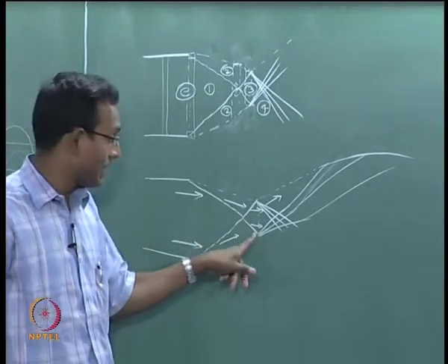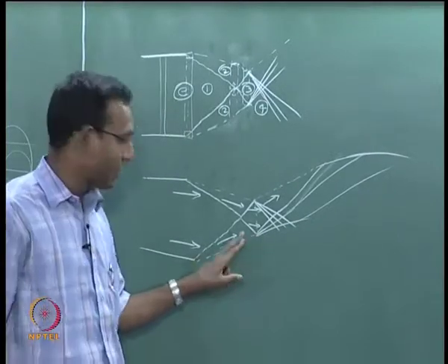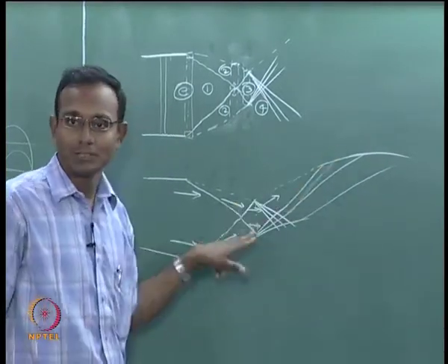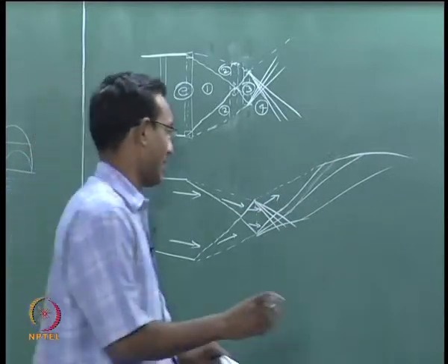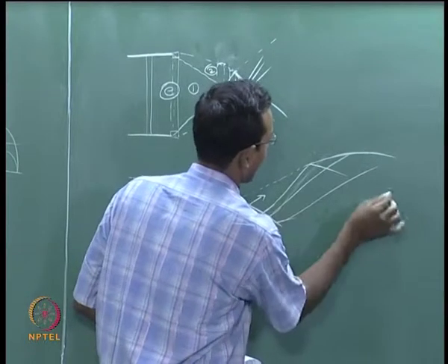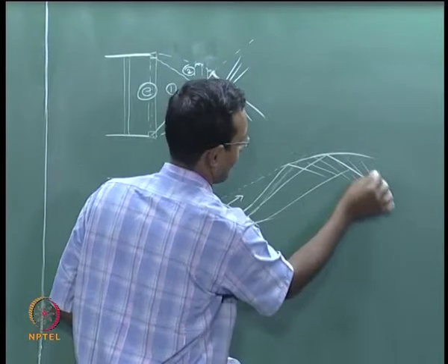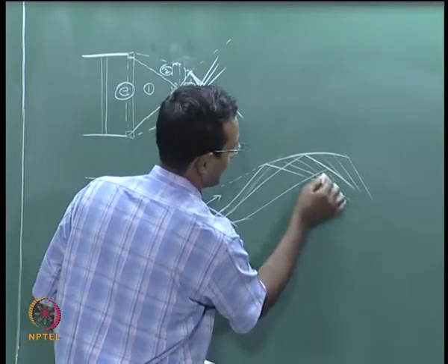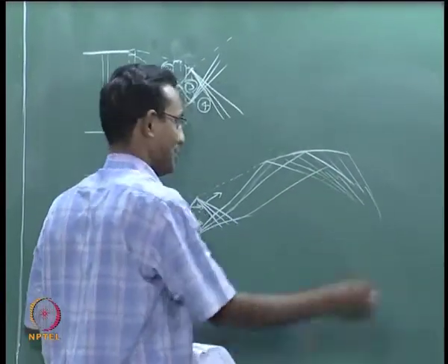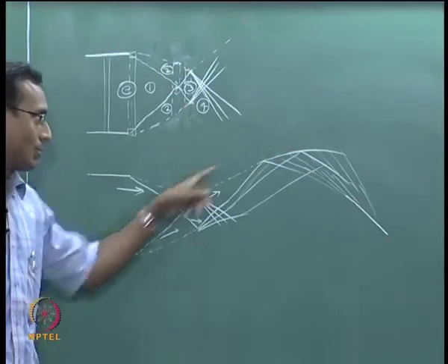So, they all have to be replaced by a whole bunch of expansion waves together at that point, and they are all running at different speeds, so they are separating out. That is a way of thinking about it. So, at every point there will be a compression wave forming, so many compression waves forming overall. What happens when a whole bunch of compression waves come together? They will eventually form a shock. They all come together and form a shock there.